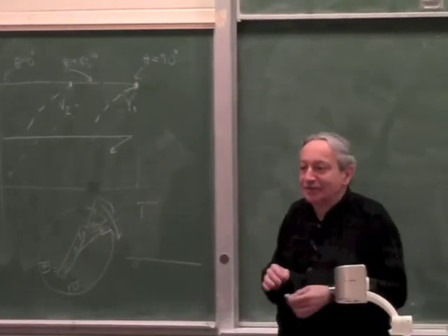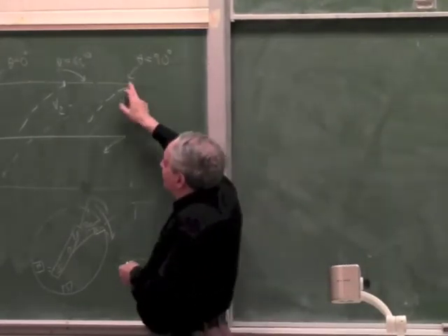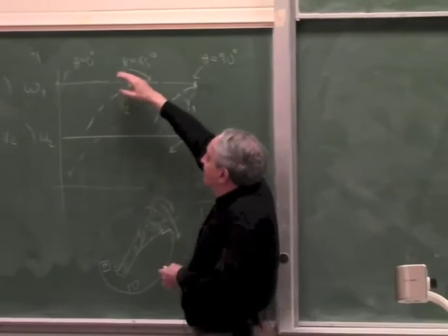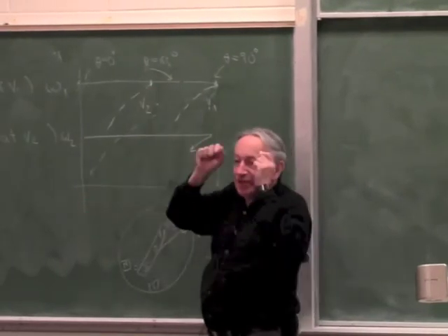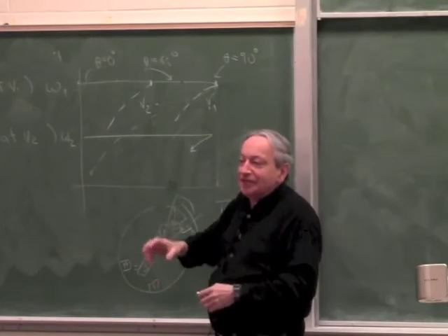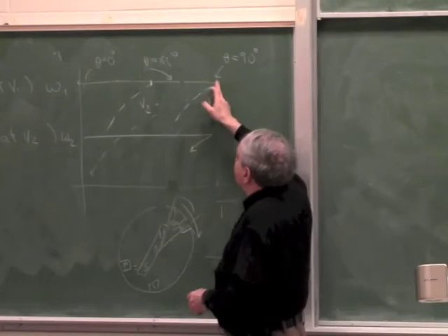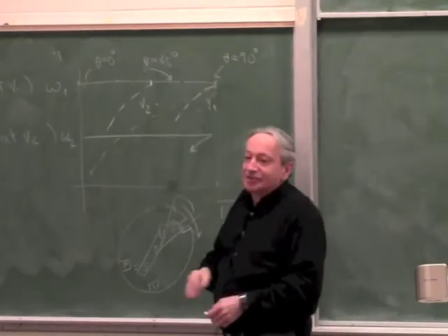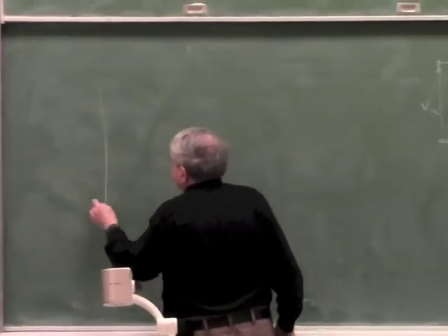They have no starting torque. Because the moment you start, omega ramps up instantly, because when you start the motor from the power line, you apply the full omega instantly. So the moment you apply the full omega instantly, it already wants to turn at full speed. Because of the inertia, it's already at this point and collapses. Good. So now let's talk about induction motor.